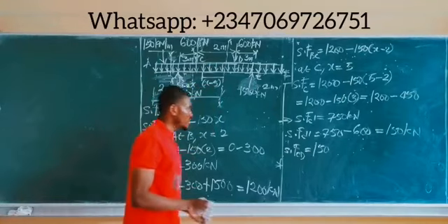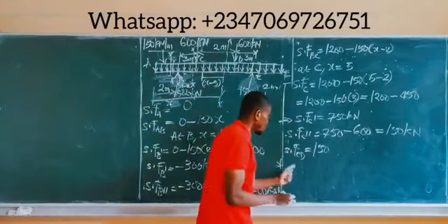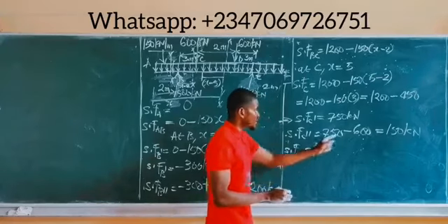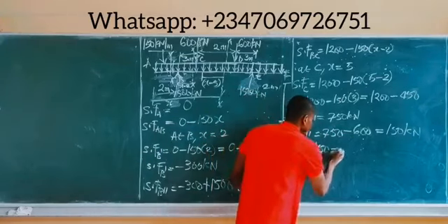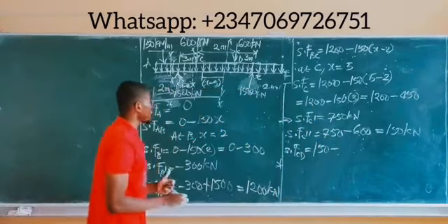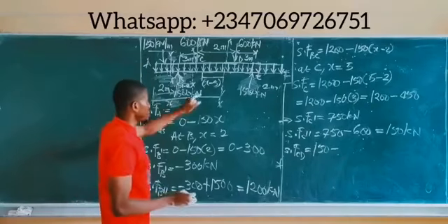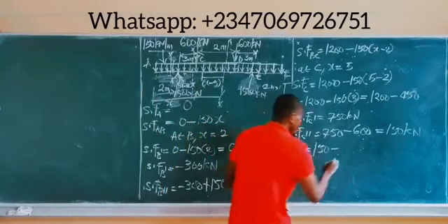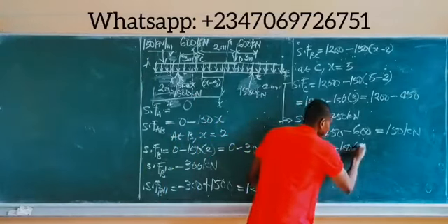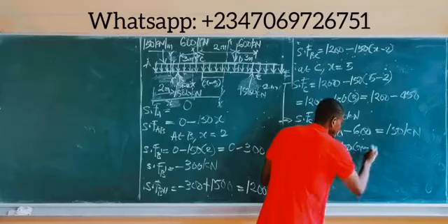So if that's the case, then shear force at C is equal to 150, which was the final shear force we had, minus, to convert the UDL to a point load, multiply the UDL intensity, 150, by the length, which is now X minus 5. So you simply have 150 times X minus 5.